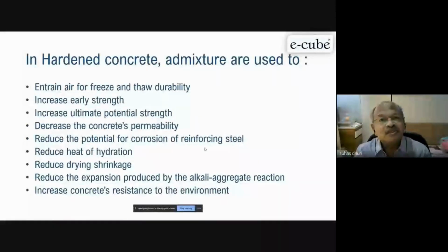If you distribute it throughout the body, it gives some stresses when concrete is in the hardening stage, not in the fully hardened. It is only set. Because when you are placing concrete at such a temperature, we have to heat everything, including water and aggregate. We have to heat, make the concrete around 10 degree, and then only it is allowed to place. Then it will harden. But then it is exposed to that freezing and thawing. These all phenomena will take place.